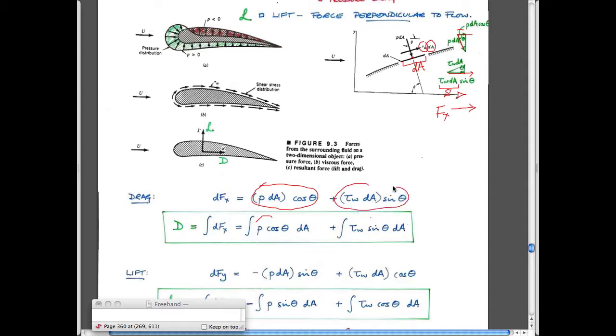So we're looking at each of those components in the x direction. This is an increment of the force. If you sum it up for all the different points around this airfoil, you have them all together. You just do it by integrating. So you integrate both sides, nothing more than that, and you end up with this expression. So the drag force that's applied to this due to both of these components, this hitting me in the chest and killing the velocity, and this squiggling past me and dragging me by the shear force due to the viscosity of the fluid, are both added up to get that.